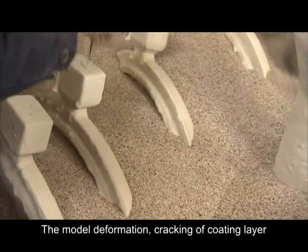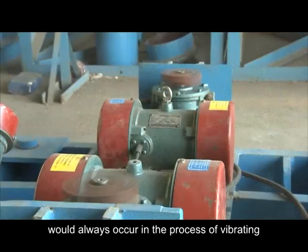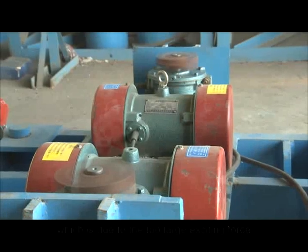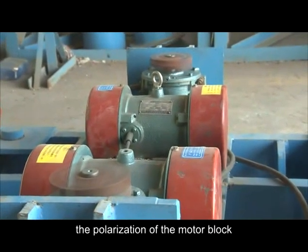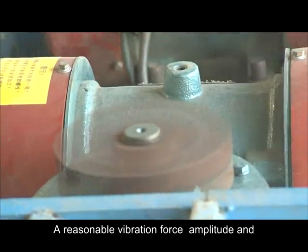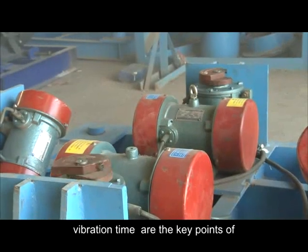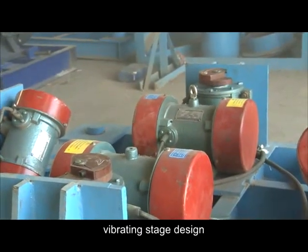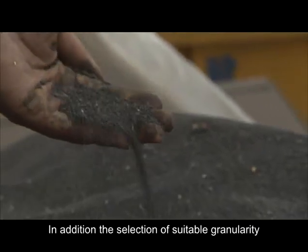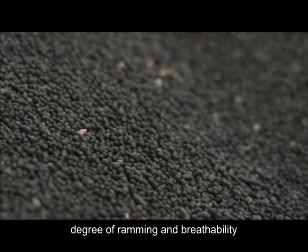The model deformation and cracking of the coating layer would always occur in the process of vibrating, which is due to too large an exciting force, or the polarization of the motor block in the same group being imbalanced. A reasonable vibration force, amplitude and vibration time are the key points of vibrating state design. In addition, the selection of suitable granularity of sand ensures both the degree of ramming and breathability.